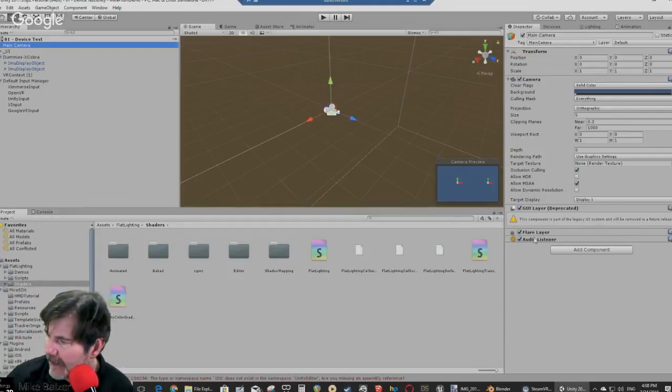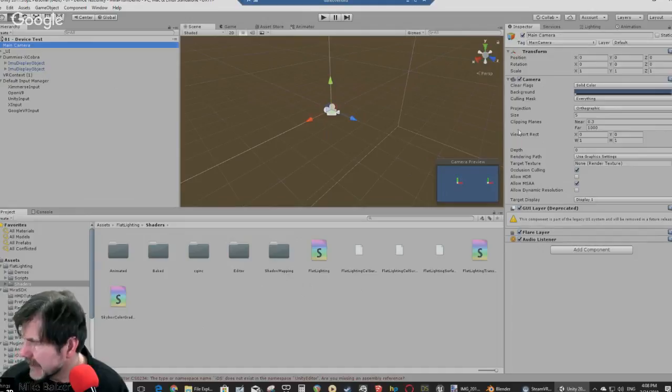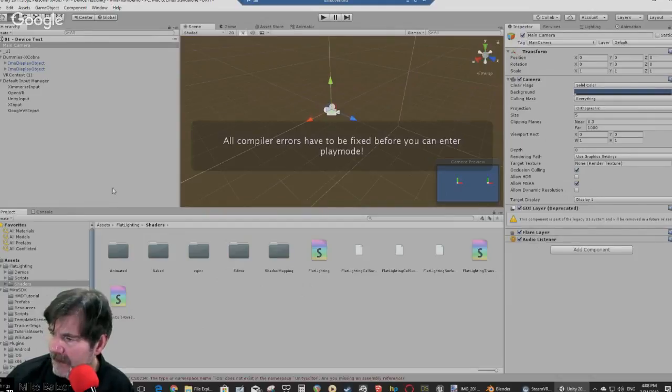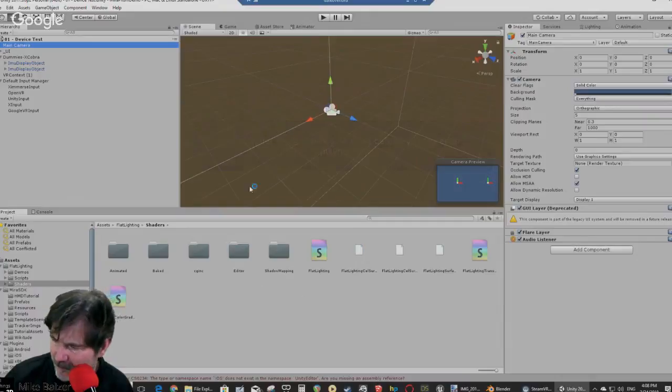I don't see it here. But if we click on that, yeah, we have a compiling error. The other thing is I've noticed that some of these systems don't keep up with the latest Unity, even the latest versions. So make sure when you are trying to work with the plugins or the packages that you match whatever build of Unity with whatever their most current or updated version that's identified in the package itself. Otherwise, it will ask you to compile them, and then you don't always get good results from that.